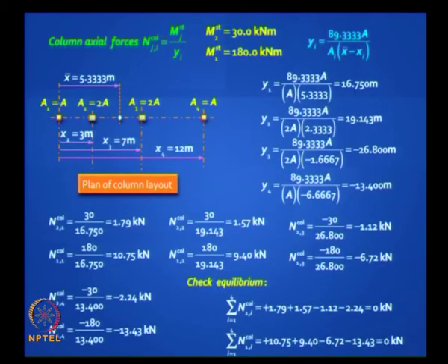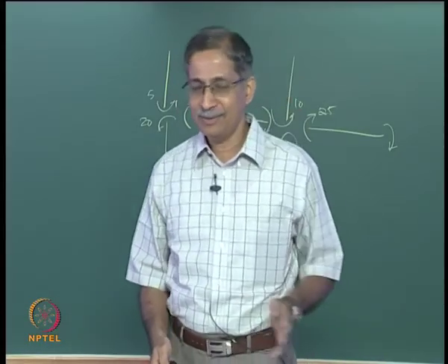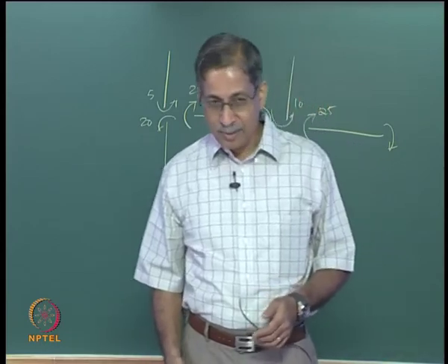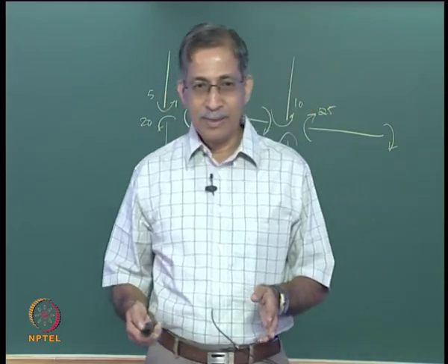So can you all do this step? Of course, I will give you the choice; you can do either portal or cantilever. For the assignment you have to do the cantilever also, but in an exam it is too much to do. In practice, both are approximate. People say the portal method is more accurate when you have a wider frame, not very tall, and the cantilever is more accurate for a very tall frame with narrow width, but it all depends on the relative areas. Okay, so here I will go quickly, we are doing the same thing.